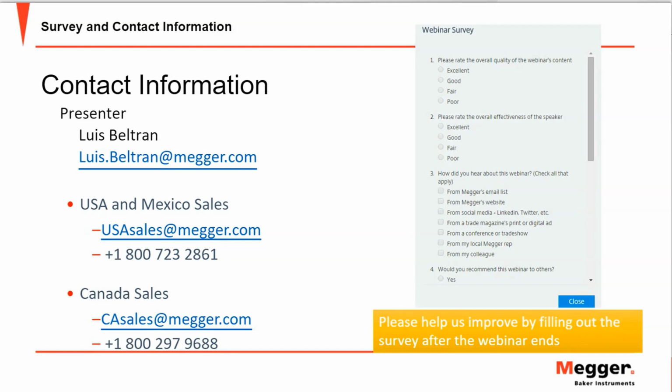Okay, so the PP, or post-pulse error, should be used anytime. I mean, you can use it whether the rotor is installed on the motor or not. But the line-to-line error, LL, cannot be used when the rotor is installed, because we will have a huge difference in waveform because of the effect of the installed rotor. There's another situation too, when we have concentric coils in a special motor, where we cannot use the line-to-line error for the calculation.